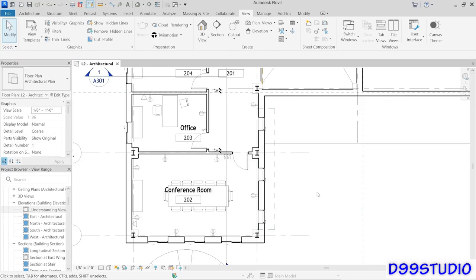And now you'll see that the clerestory windows are displaying within that little zone only, and the rest of the plan is unaffected. So hopefully that quick example gives you some idea of how the cut plane in the view range functions, both globally across the entire floor plan or in an isolated region should you need to do so.